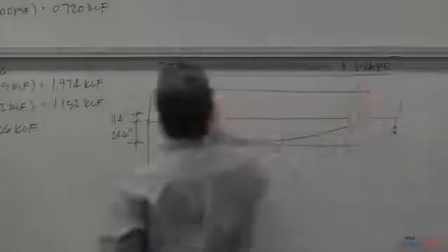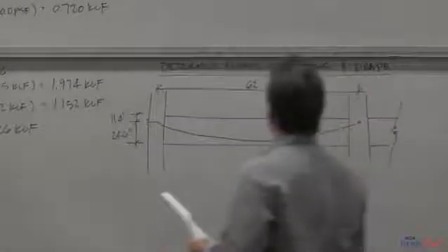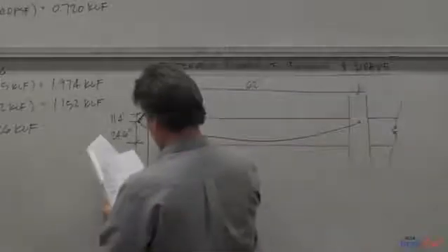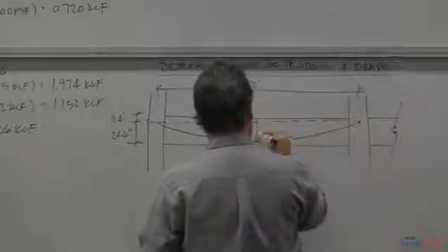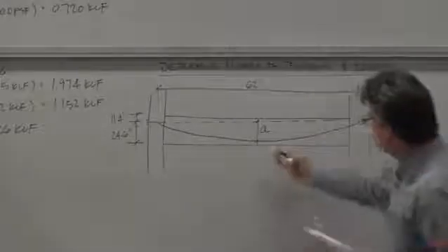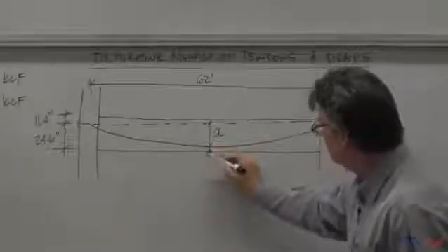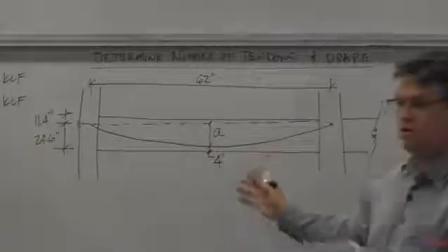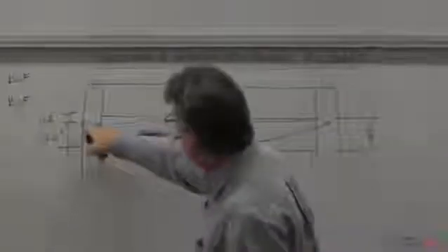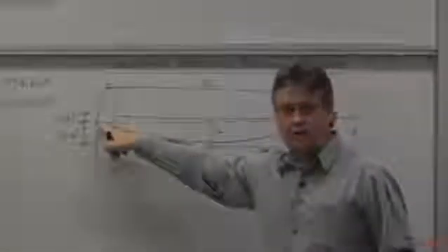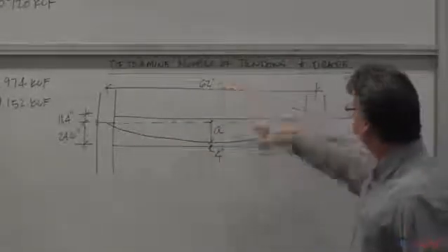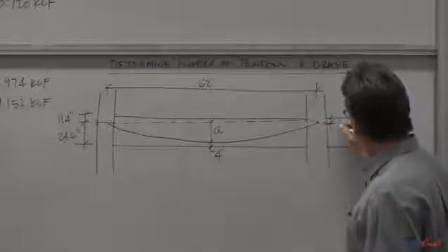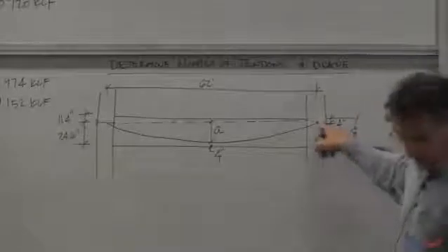Okay, I'm in the long span at 62 feet. What am I going to put for the distance to the bottom here? 4 inches. This is the controlling span, so I want to go as high as I can. I want to be at the center of gravity of the concrete at the end. We don't want to have any applied moments. I'm going to fully drape this span because it will be the controlling long span. It tends as high as it can get over the support, 4 inches from the top.